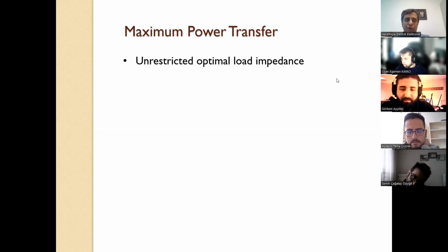I would like to tell you one more thing. This is not the maximum power transfer, actually. Now we know quite a lot about power calculation. It is actually maximum average power transfer. You should understand the reason, because the average power is converted to work.